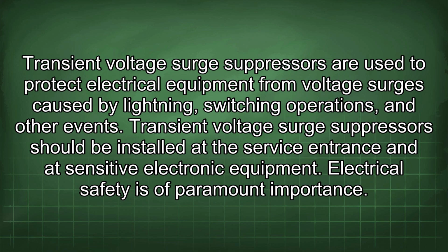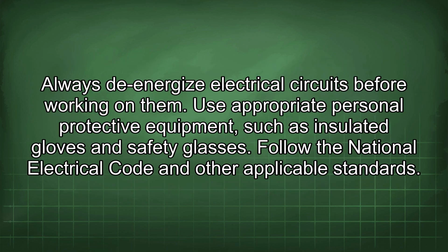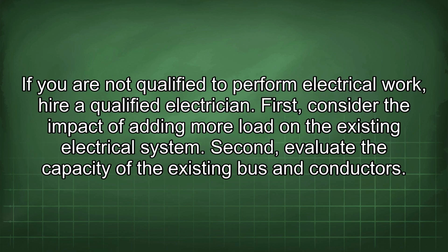Electrical safety is of paramount importance. Always de-energize electrical circuits before working on them. Use appropriate personal protective equipment, such as insulated gloves and safety glasses. Follow the National Electrical Code and other applicable standards. If you are not qualified to perform electrical work, hire a qualified electrician.